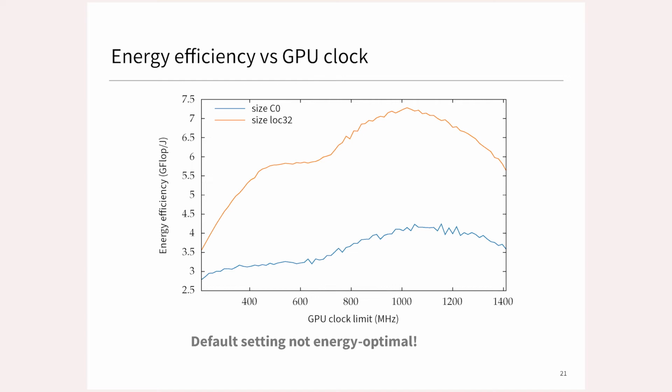to rank systems. And what you can see here is that the energy efficiency is higher for slightly lower frequencies than the maximal one. It is a proof of something which I think is generally well known, that the default setting of this processing chip is not optimal if it is set to allow going to the maximum frequency. Essentially, this plot could be enough and could be the result, and you could pick on this graph saying, well, maybe you should go to 1 gigahertz because then you get more stuff done for each watt hour spent on the machine.